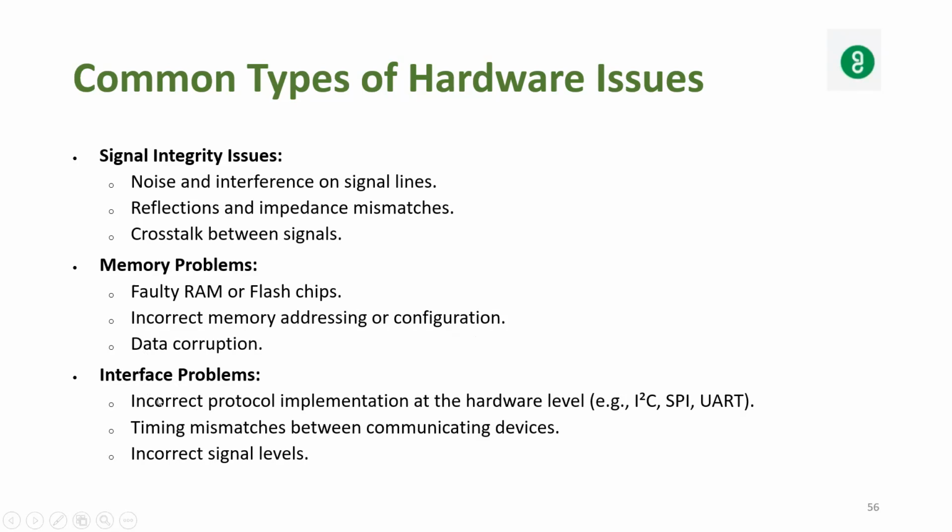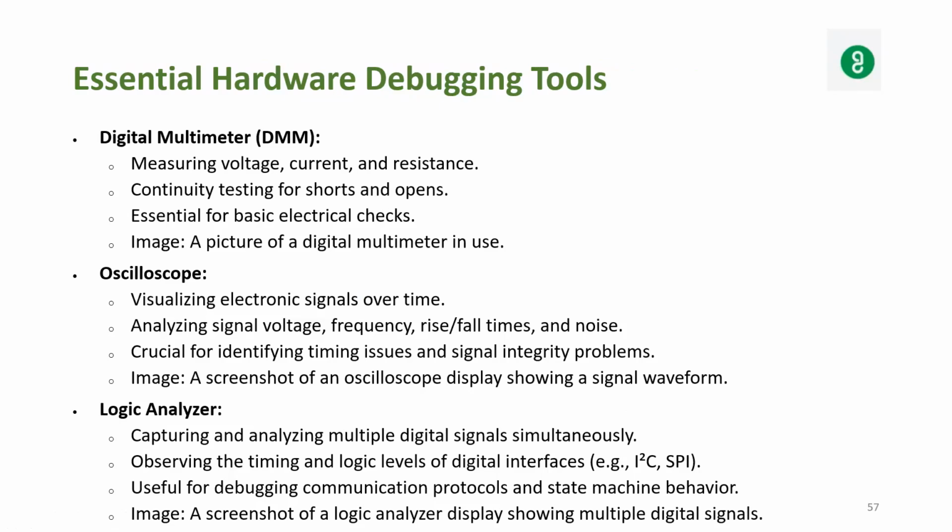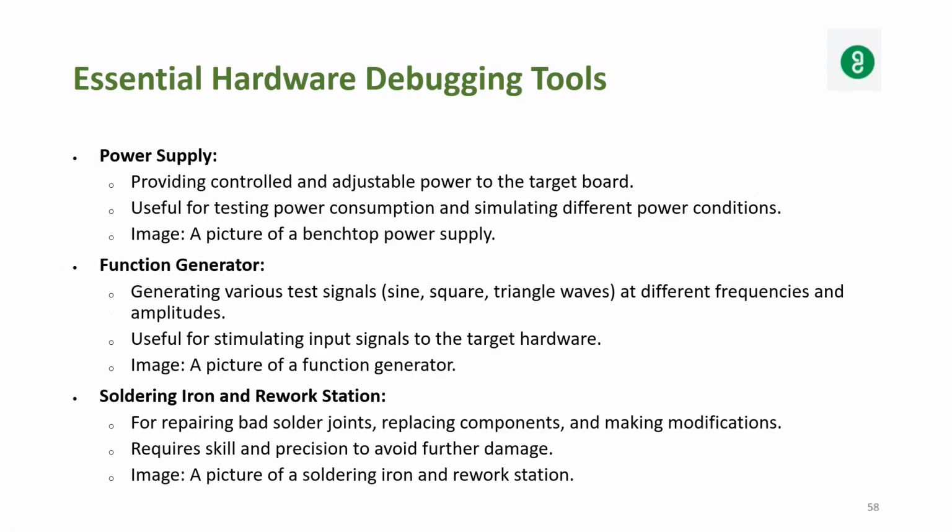Interface problems: incorrect protocol implementation at the hardware level, for example I2C, SPI, UART, and timing mismatches between communication devices. Incorrect signal levels.